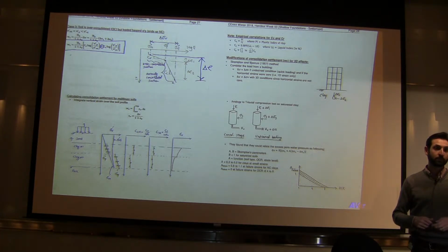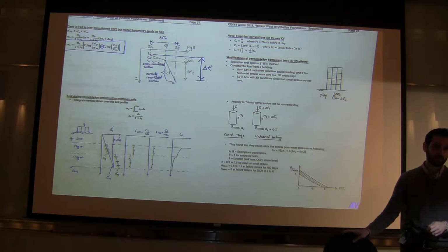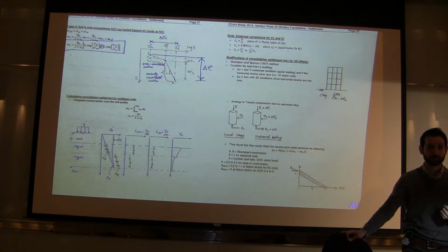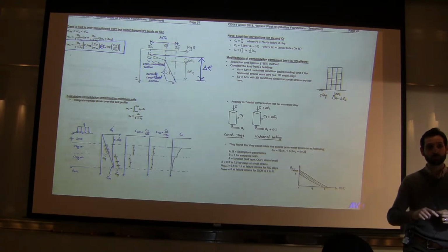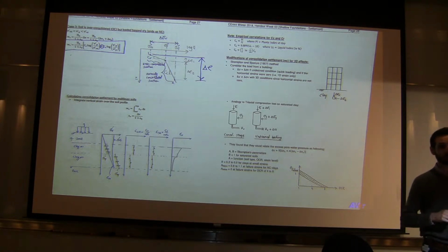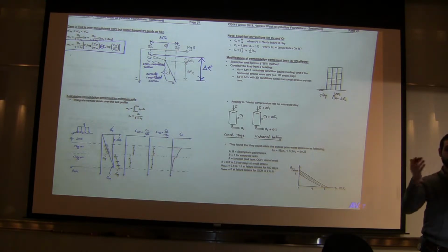So you can do one CPT of 100 feet long. Usually for seismic studies, we do a lot in Portland now, because a lot of places have to bring their standards to the Oregon Resiliency Plan. So a lot of geotech firms are involved with seismic studies. And for seismic studies, you want to reach bedrock, because that's how your seismic evaluations start. You need to know where the bedrock is. And so oftentimes we end up doing CPTs that are pretty long and deep. So you may end up doing just one CPT a day, and that would cost $2,000 to $5,000.